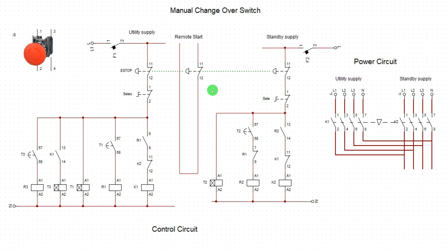If you are not able to set the panel, you introduce your own on the ATS. After building your ATS, providing this cooldown duration, you set your own cooldown for like 1 minute. If you discover that the genset also has a cooldown duration of 3 minutes, that means 3 minutes from the genset and your 1 minute, making 4 minutes, that one is too much. So how do you do? Either you disable your own or you disable the one on the genset. Later I'll tell you how to do that.